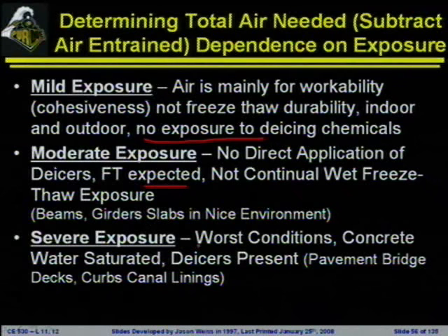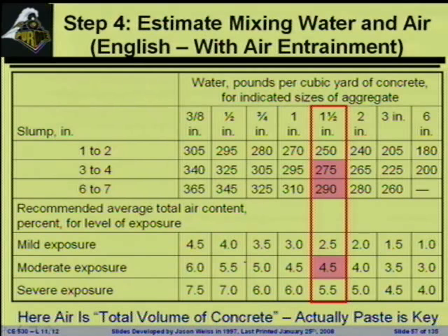Severe exposure is the worst condition. This is going to be the pavement, the bridge deck. This is going to be the loading dock slab outside of the building where they're dumping full bags of sand out there to keep people from slipping, and it's constantly covered in water. This is really the worst condition, the severe condition like you would expect.